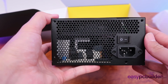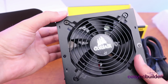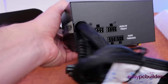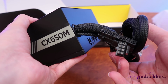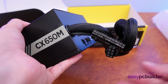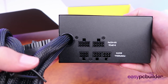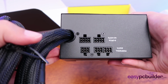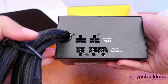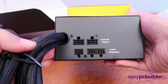On the back of the power supply here, we've got our power in, our power isolation switch, our fan, and on the front here we actually have our minimum power connectors hardwired into the power supply itself. So we've got our 24-pin motherboard connector and our 8-pin CPU power connector. As this is a modular power supply, the additional cables to power the graphics card and other external or internal SSDs and hard drives are optional, and you can connect them into the power supply as you wish.